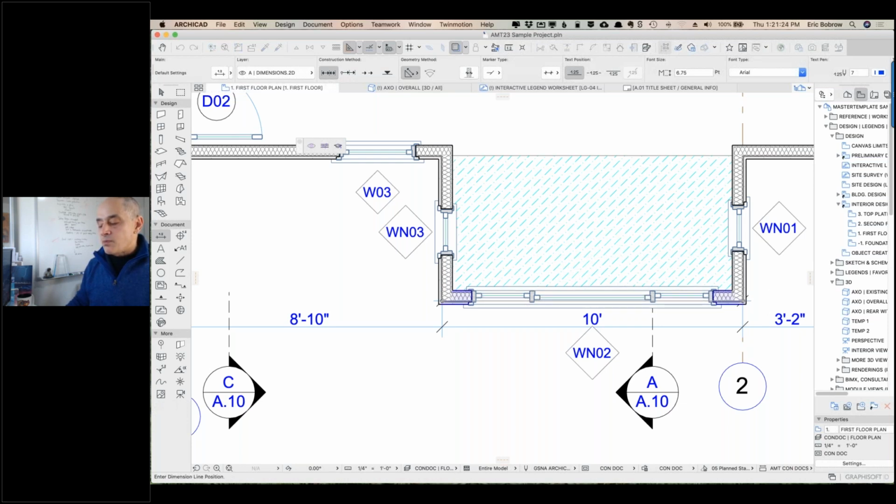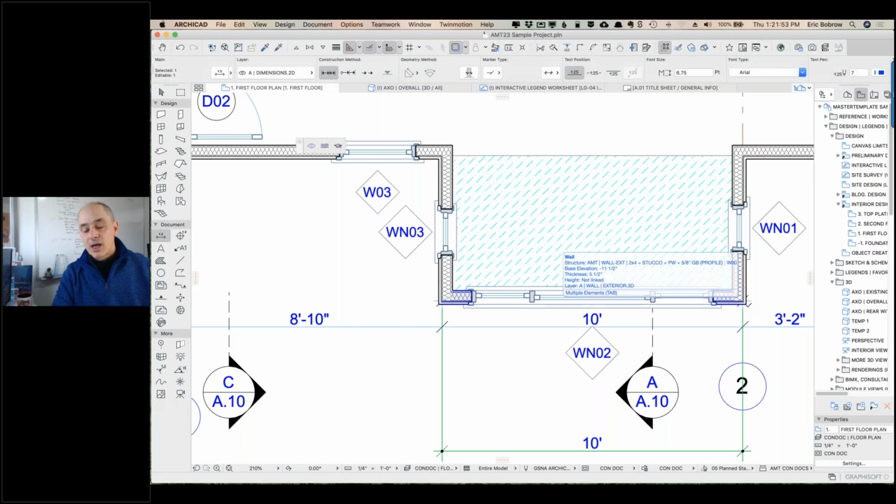I guess if I now click on this, did I get a dimension? Yes, it is actually here. This dimension is hidden. You can see that there is a line across there. That was what was confusing. So I placed it right on top, and then if I do the drag command and take this down, I could say that I wanted it to be 5 feet away here. So that is 5 feet away. So it's a little bit cumbersome.